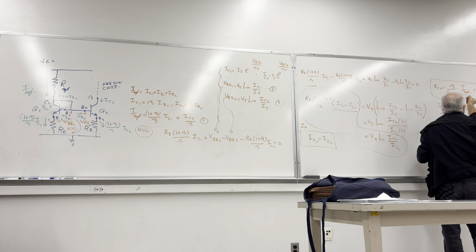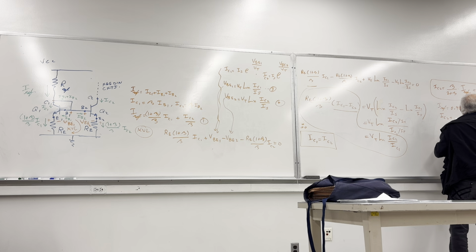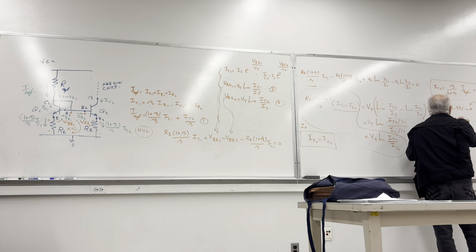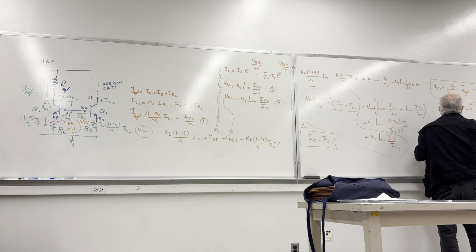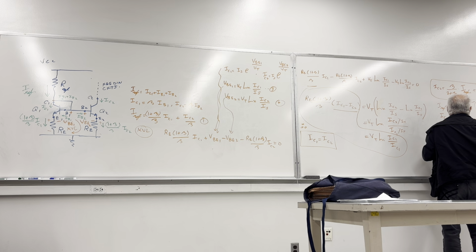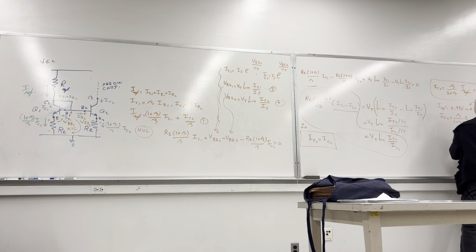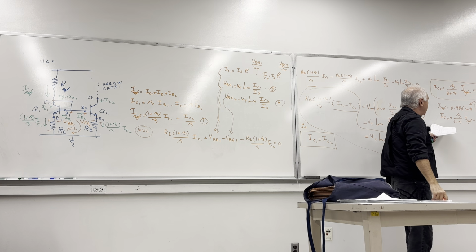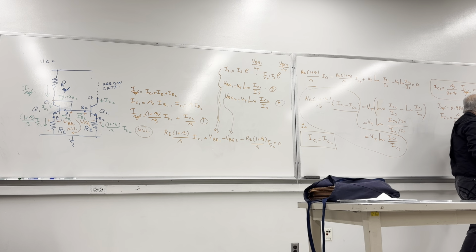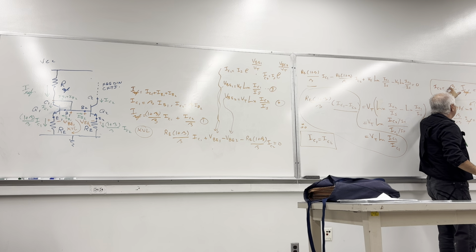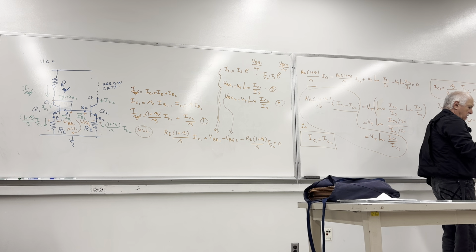Then you calculate IC2 by that equation, number 10. This is from 9. We get that. Then from IC2, you will have beta over 2 plus beta times IREF, which is 100 over 102 times IREF, which is equal to 0.967 milliamp. Pretty close to that one, but a little less. It should be a little bit less because the numerator is smaller than the denominator.